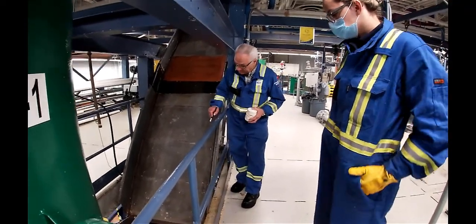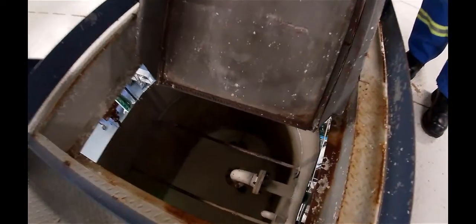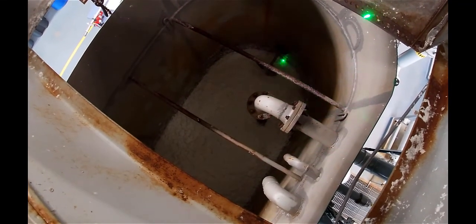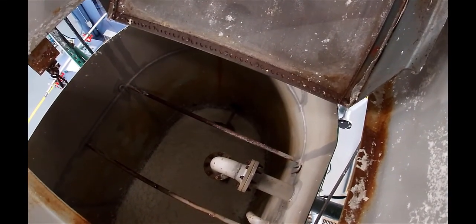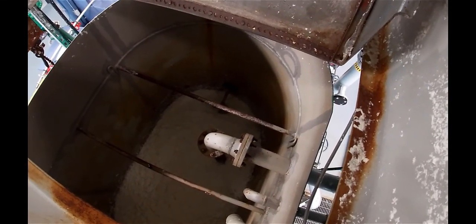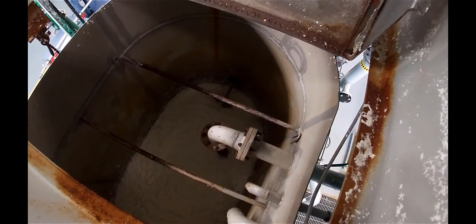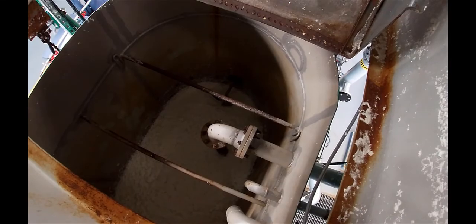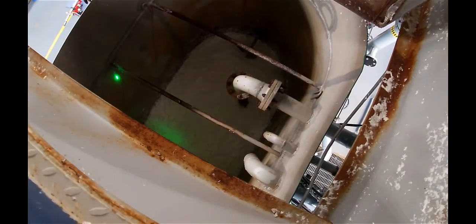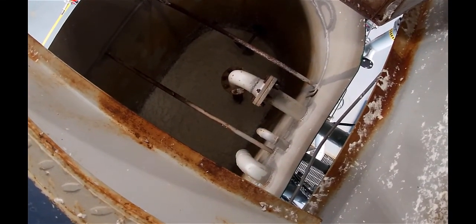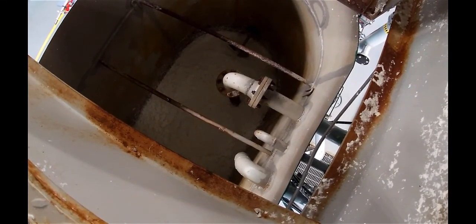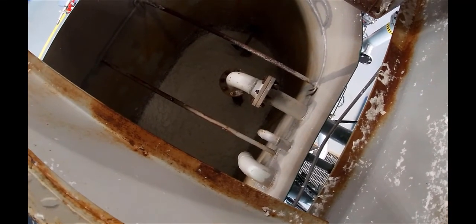In the bottom of the tank right now, and Ray, if you can just get a picture of that, there is the one batch of stock that we dropped down in here, and it's still below the agitator blade. There are the main agitators. Probably by the time you get 4 batches in there, you would be able to start up the agitators. You don't want to start them now, because they would just spray that stock all over the place. As you can see, it's splashed all over the inside of the wall. These pieces of metal going across the tank are stays, which keep the top of the tank from wiggling when you have stock moving around in there. So the stays are there as supports.